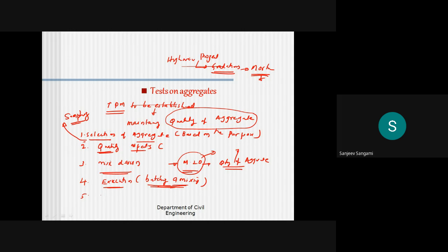Then once it is executed, supervision as well as workmanship is also very important. Once after execution, till curing period, at least proper care has to be taken.